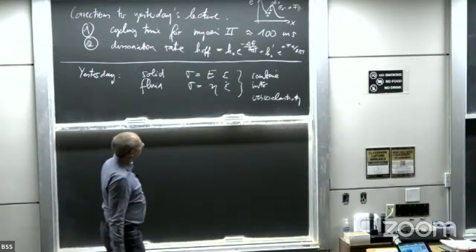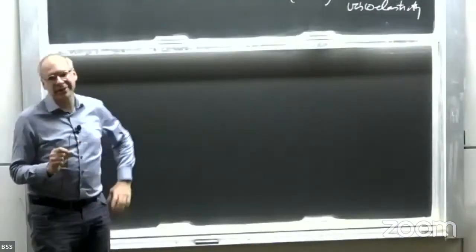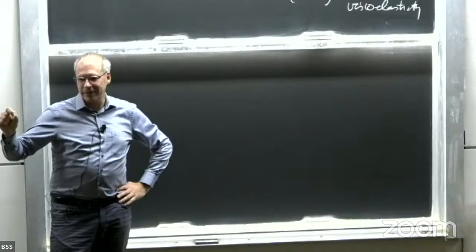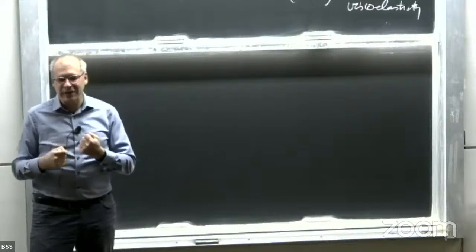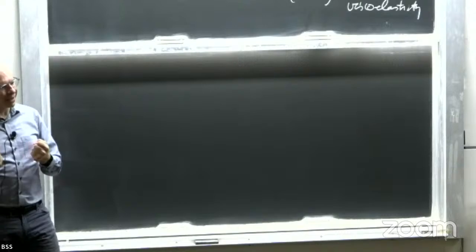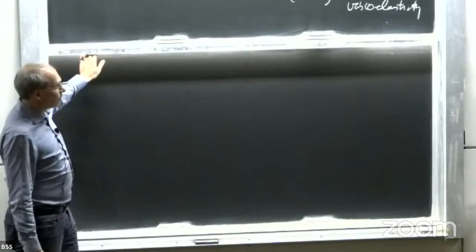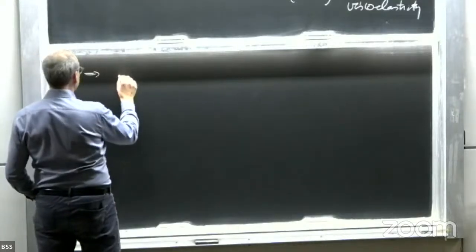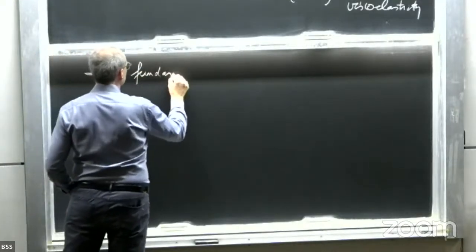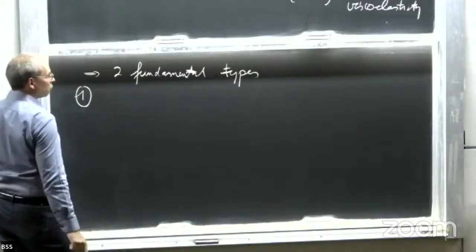So the first thing we have to understand is that if you start combining these systems, you still have to make a clear statement if in the long run it will be a fluid or a solid, because these are two different things, okay? It's not that viscoelasticity is just in between. In the end, there has to be a clear structure in the system such that it either stays rigid or it's floppy, okay? Or it's actually plastic or flowing. So there's no way around somehow specifying this. And this means that we have two fundamental types of viscoelasticity. And we are now going through them. So the first one would be a viscoelastic fluid.